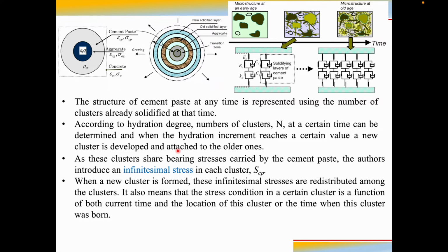As these clusters share bearing stresses carried by the cement paste, they also introduce an infinitesimal stress, meaning very small stress, in each cluster, and it is written as SCP. When a new cluster is formed, these infinitesimal stresses are redistributed among the clusters, and it also means that the stress condition in a certain cluster is a function of both current time and the location of this cluster, or the time when this cluster was born.